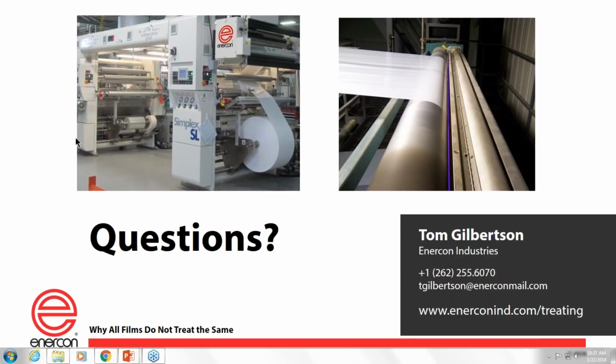Does the gapping between the treater bar and ground roll have any effect on watt density or dyne level? Now that's again a great question. I'm glad that was asked because I get this question all the time. No, the air gap has nothing to do with respect to the watt density or the dyne number of the process.